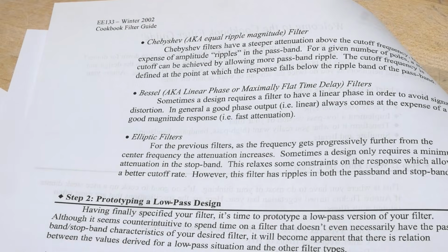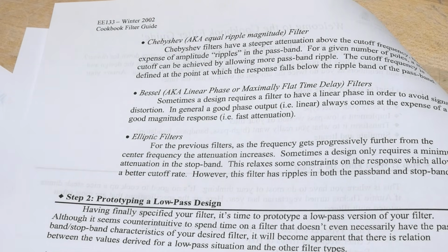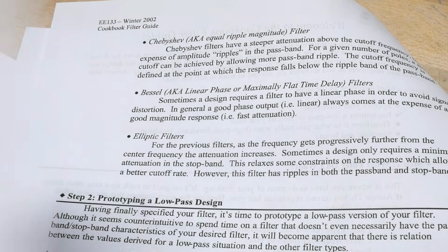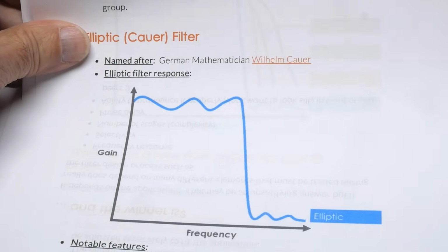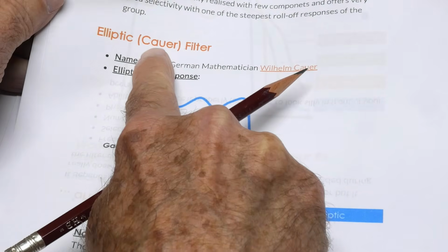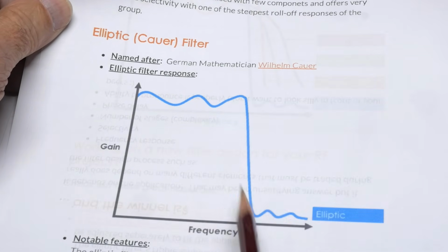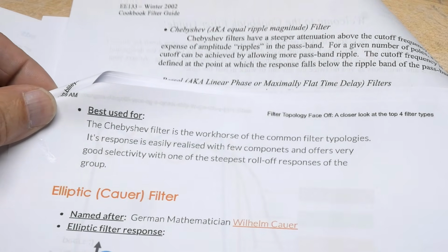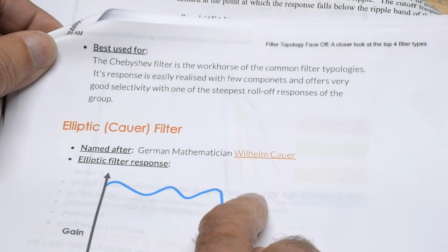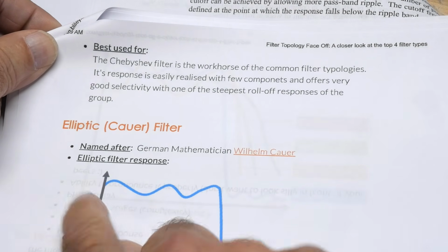So if you take a look at all those together, all together now. Here's the Cauer filter. It's spelled C-A-U-E-R. So the elliptical filter will have wigglies and then other wigglies. So it's a wiggly filter as well. The Chebyshev filter has equal wiggles. The elliptical filter will have unequal wiggles. All right?